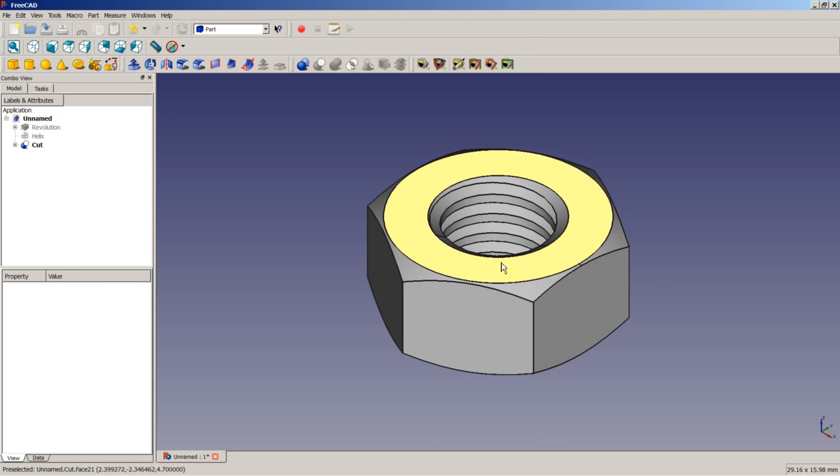So in that case, I applied via placement a 90-degree turn to the helix and the sweep profile. So the helix and the sweep profile began on the YZ plane, and suddenly the Boolean cut worked. This would be another trick you can use.